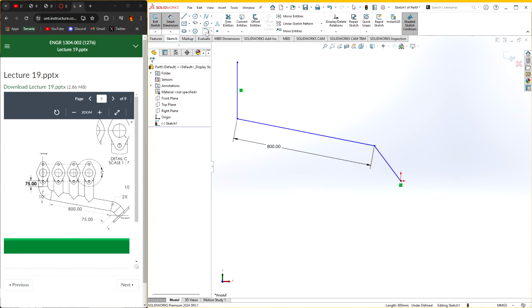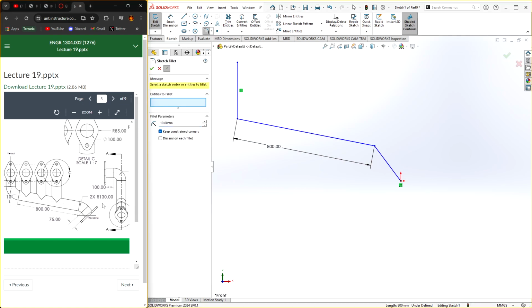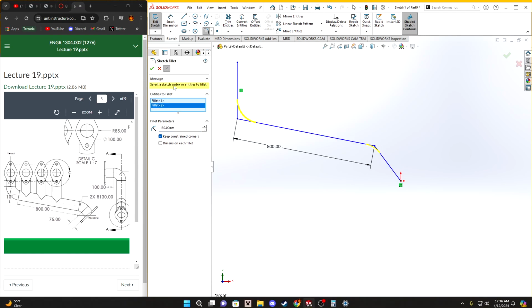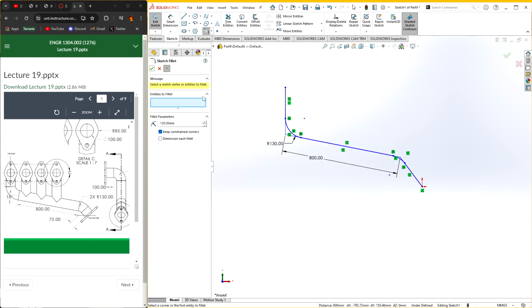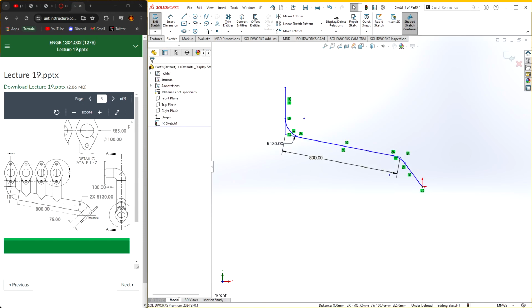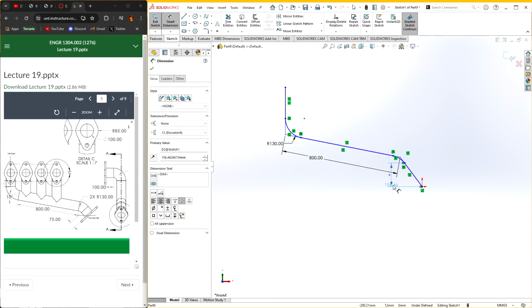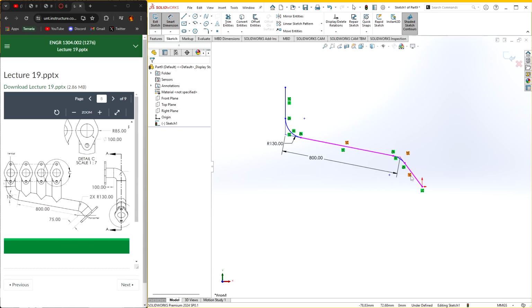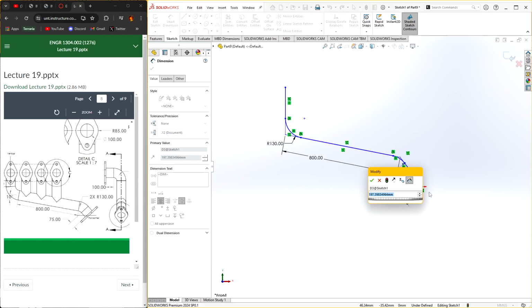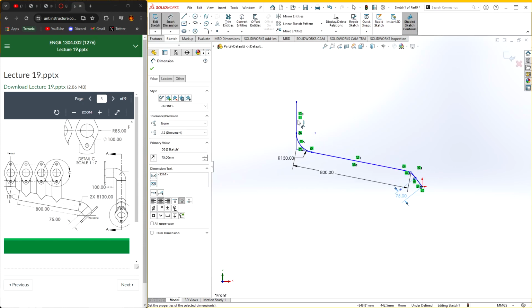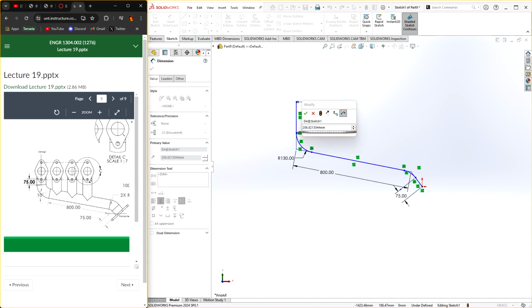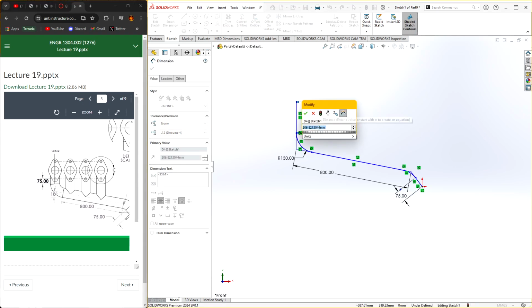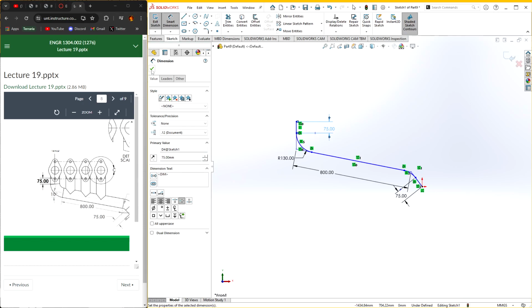Okay. Once we do that, we're going to do the fillets on the corners. So this has to be 130 millimeters. Has to be here and here. Yep. After that, we can set the length for this to be, whoops, not like that. I need this to also be at a slant. Like this. We need to set this to be 75, and this one to also be set to, I believe, 75. Yes. Okay. Just like that.